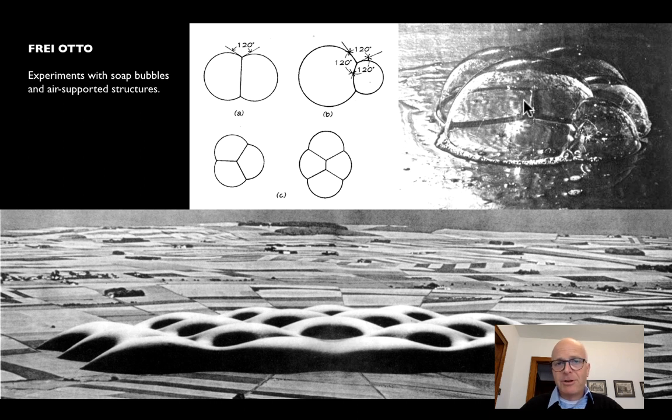And so these are very, very efficient. They use the least possible material, and when inflated, the circular geometry here is actually right. The dead weight of the membrane, in this case soap, is really trivial compared with the force being exerted by the trapped air. And therefore, instead of looking for catenary shapes or parabolic shapes in pneumatic structures, we really are looking for circular shapes, or to be more accurate,